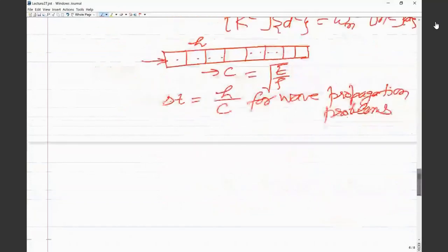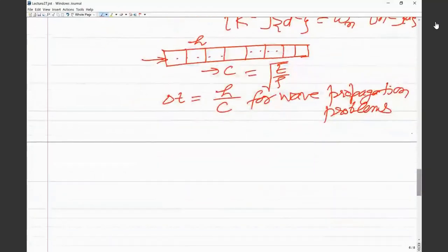So in the explicit technique, that's one way you have some guidance. Usually in the explicit techniques, the delta T is governed by stability, and because it is usually much smaller, the solution will be accurate. So that is how you handle this delta t in case of explicit techniques.